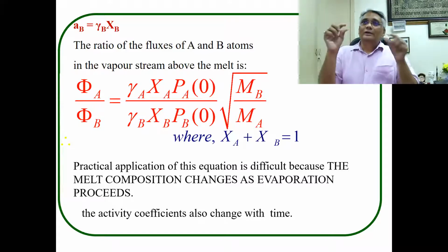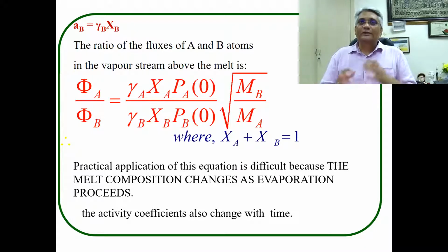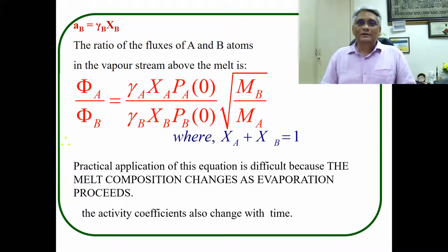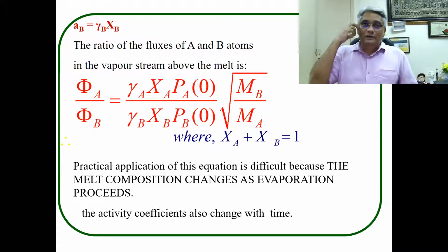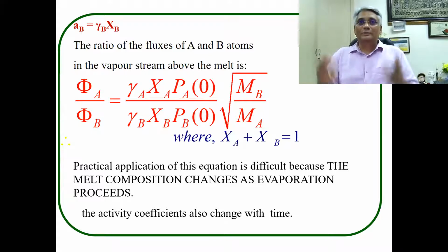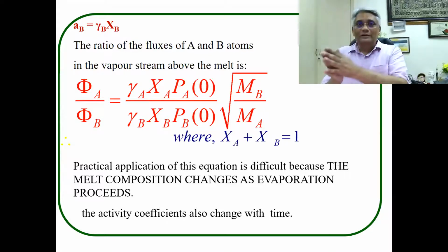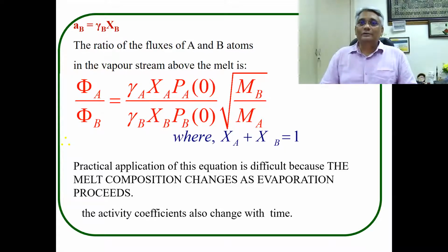If you have an alloy charge of say 10 grams, and for the given initial thermal energy, you know how much time it takes for the entire alloy melt to vaporize and form into a thin film, right? It can't happen in a split second. So there's a time scale involved. Within that time scale, you will see the activity coefficients changing.